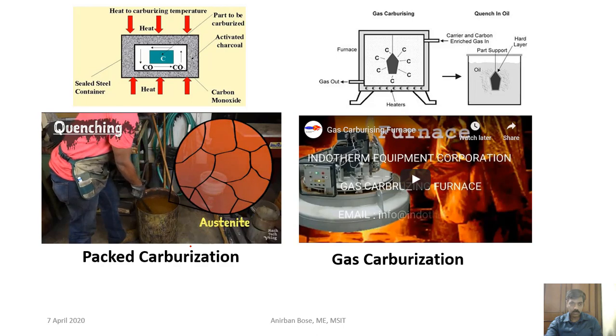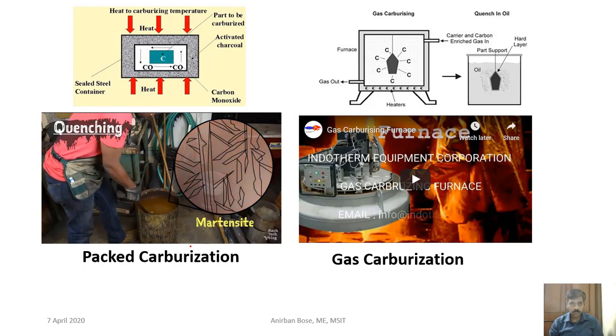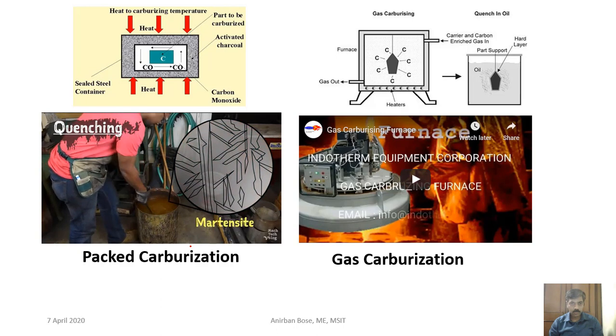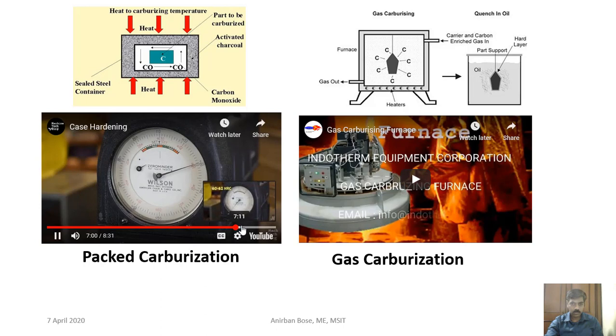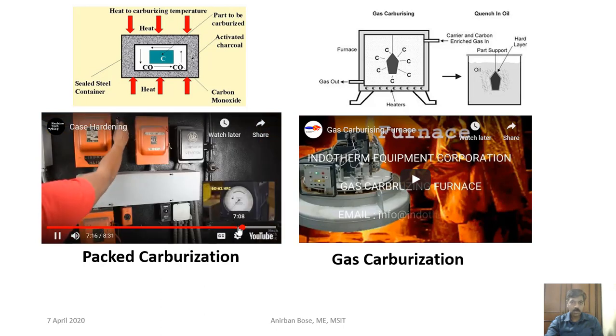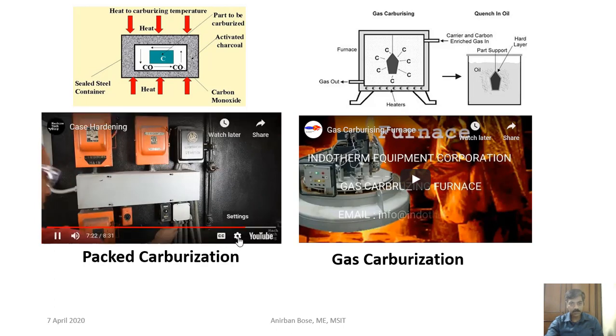Because we're cooling the steel so rapidly, the austenite won't have enough time to separate back out into iron and iron carbide. The resulting steel microstructure, called martensite, is composed of needle-like shards of iron supersaturated with carbon. Martensite is very hard but brittle, so we temper the parts by heating them back up to a relatively low temperature and holding them at that point for some amount of time.